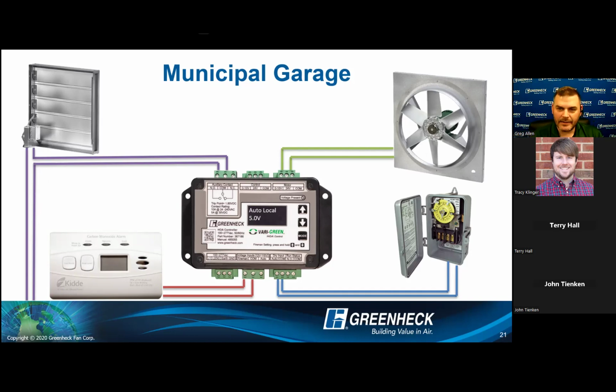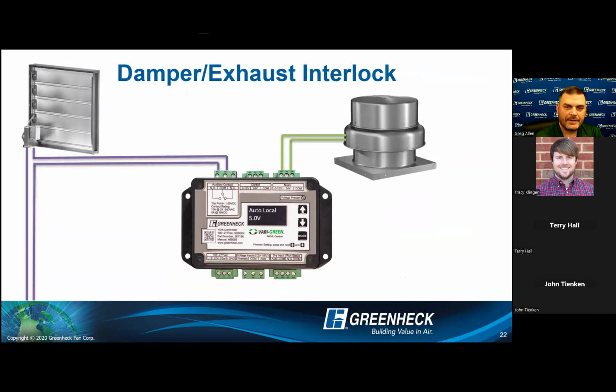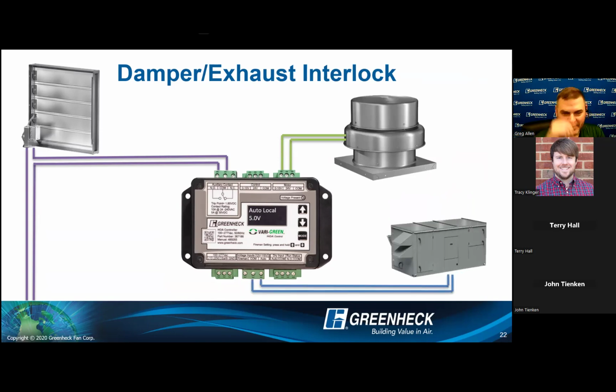Carbon monoxide alarm systems, I've seen them both ways, both dry and voltage inputs. So, all right. That's a good application to show off how all these different things can work together without a super brain computer being part of the building. This is just your damper exhaust interlock. Kind of wanted to point that out.